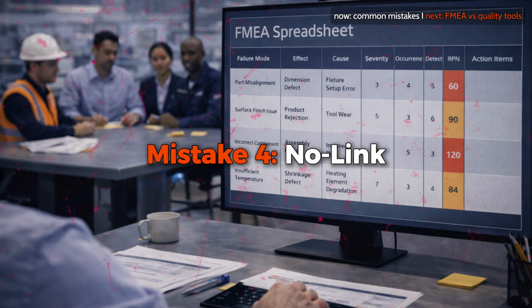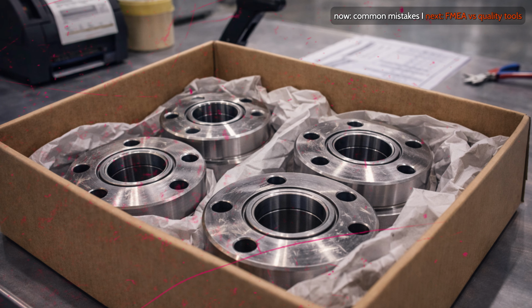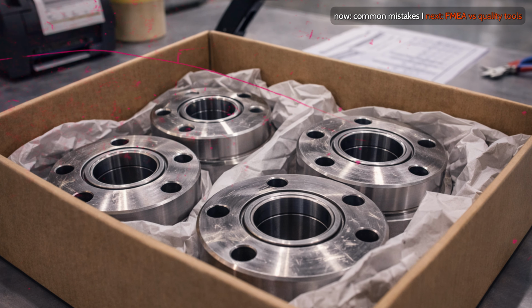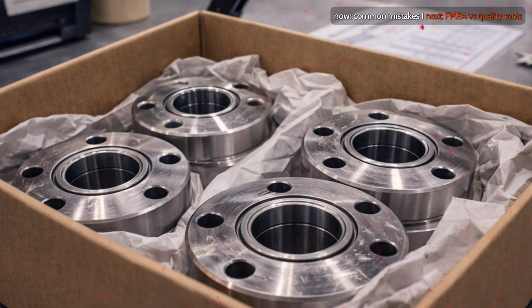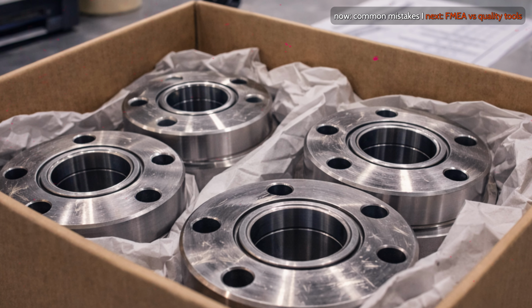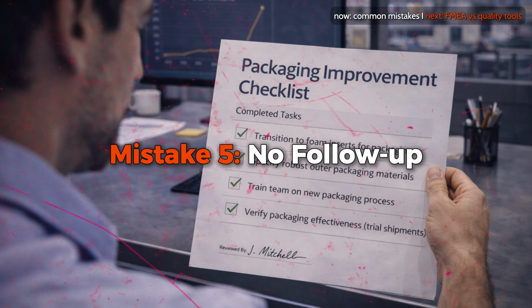Mistake 4. No link to real controls. If the FMEA identifies scratches as high risk, but no protective packaging is implemented, the document becomes theoretical. Actions must be implemented, verified, and reflected in the control plan. Mistake 5. No follow-up.